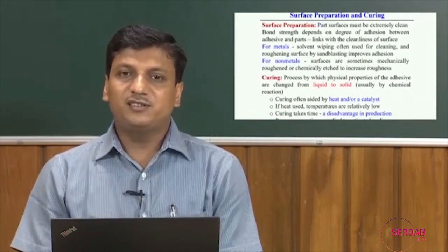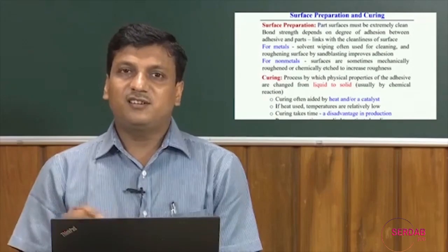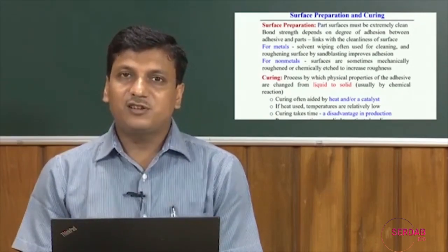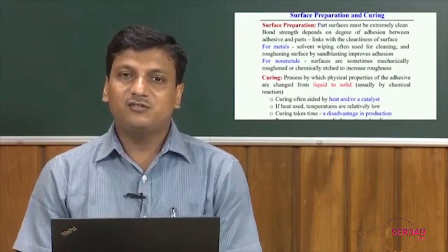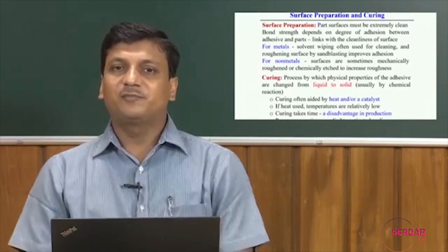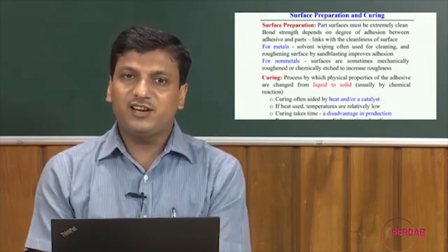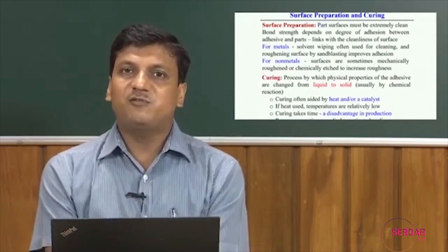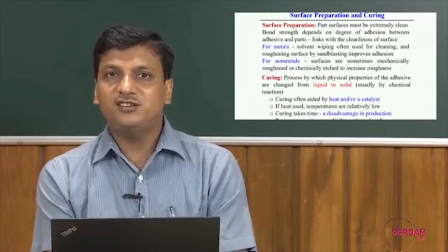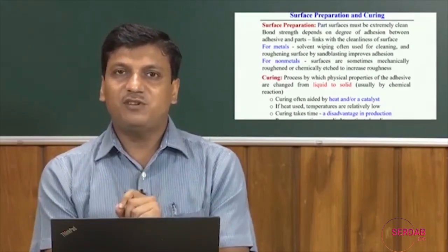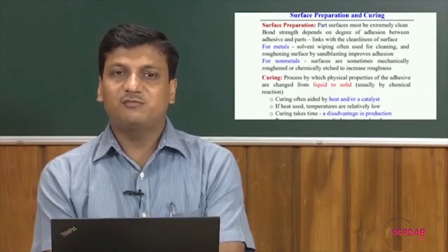But for non-metals, the roughness is improved sometimes mechanically, or sometimes we can use a chemical etchant to increase the roughness. So, in general, the surface preparation for adhesive bonding is, first, cleanliness. Second, some sort of roughness should be present on the surface.